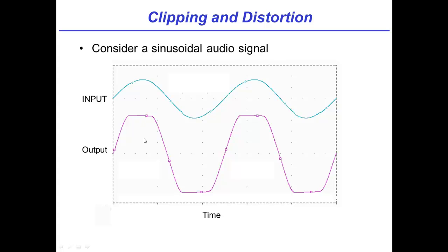So how does this relate to distortion? Okay, well, you've actually sort of set this up for me very nicely. Well, thank you, Vivek. When we think about audio, the fundamental construct we use to build audio signals is, of course, sinusoids. Right. A single sinusoid you hear as a monotone, as a single frequency. When you clip it, you know from your past experience, perhaps looking at Fourier transforms, etc., you've learned that this signal is clearly not a sinusoid, but in fact you can build it as a construct of multiple different sinusoids.